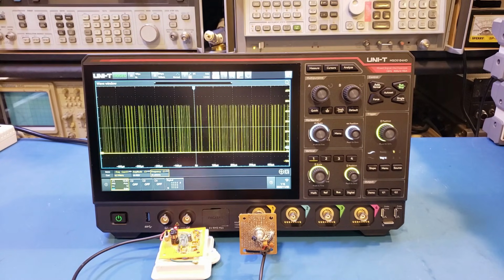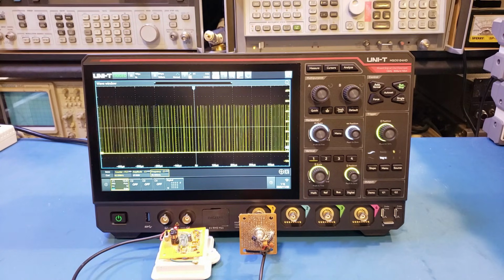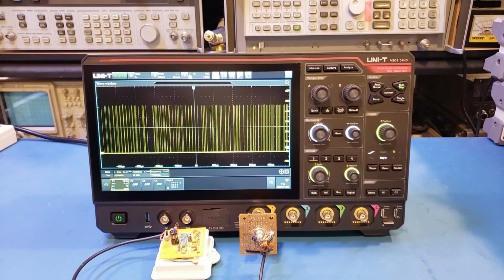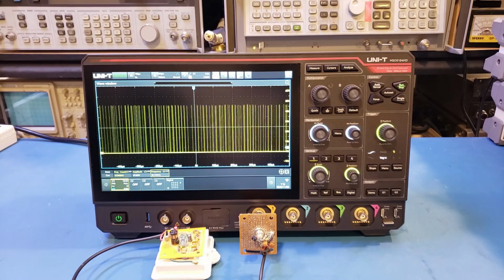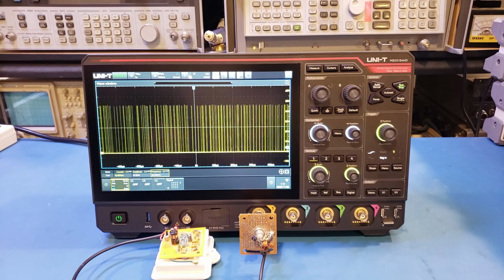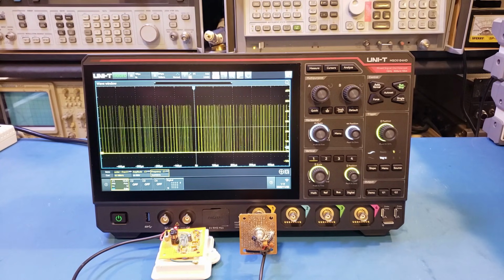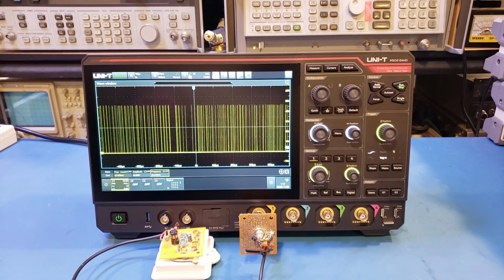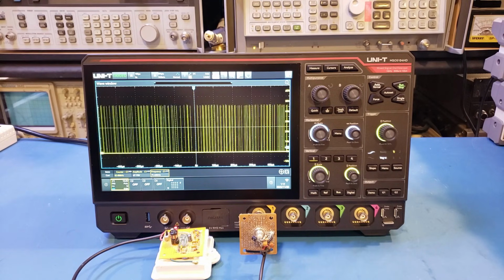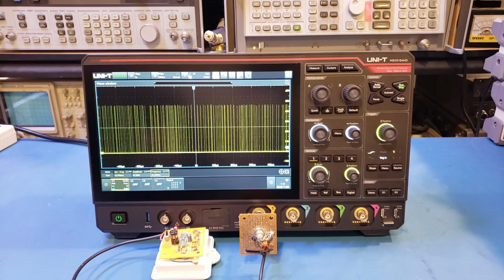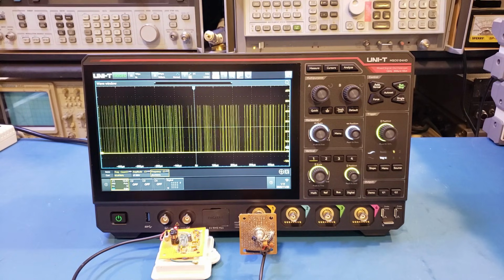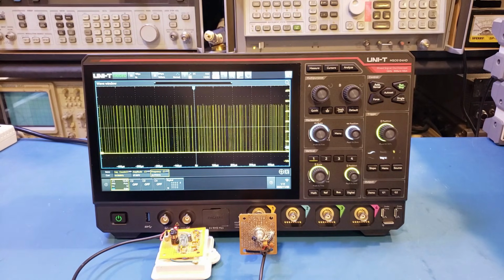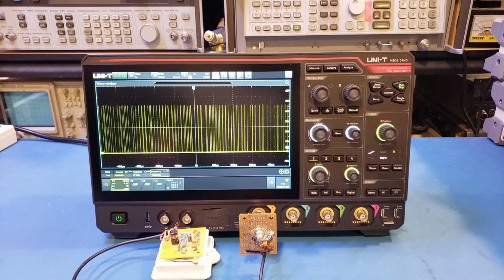I actually don't quite know the rise time of the Avalanche pulse, just because I never had a scope fast enough. Now with this 1 GHz bandwidth scope, I think I may be able to infer the rise time of the actual pulse. In my review of the 300 MHz bandwidth MSO5304X, I knew I was pretty close to the limit of the Avalanche pulse generator because the rise time is right around the limit of the bandwidth. And on the 500 MHz scope I tested, the obtained bandwidth is actually lower than 500 MHz, so I know the rise time is probably not that much faster than 1 nanosecond. But this time we have a much higher bandwidth scope, so we can validate that.